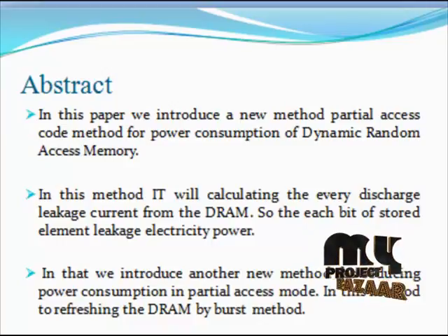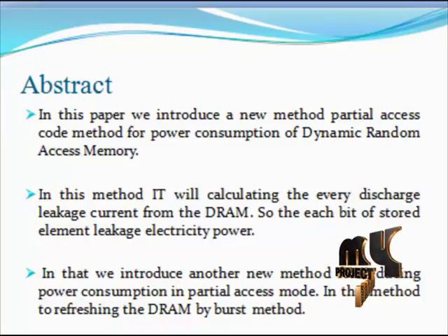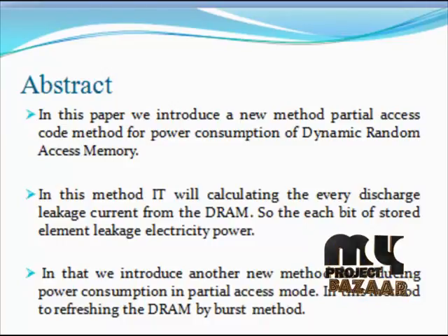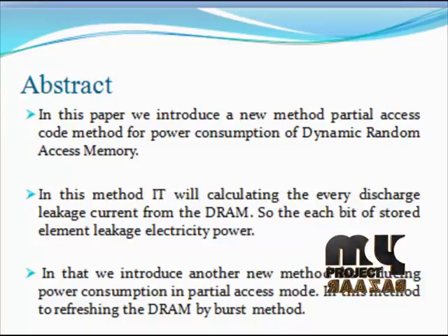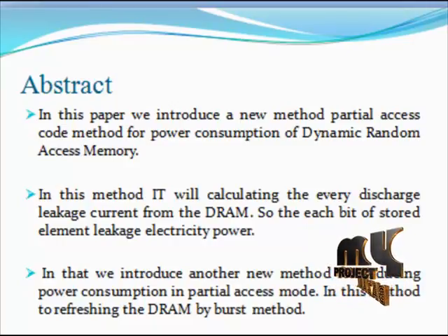standby currents. When a system uses DRAM, a refresh operation is necessary because of its data retention time restriction. Each bit of DRAM is stored as an amount of electrical charge in a storage capacitor that is discharged by the leakage current. Power consumption for the refresh operation increases in proportion to the memory capacity.